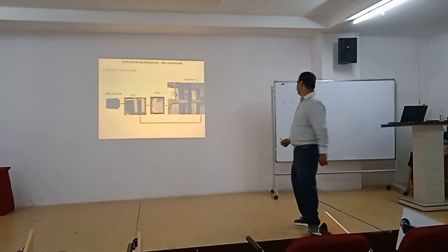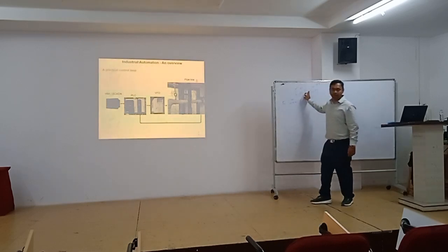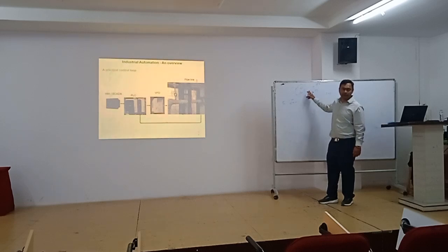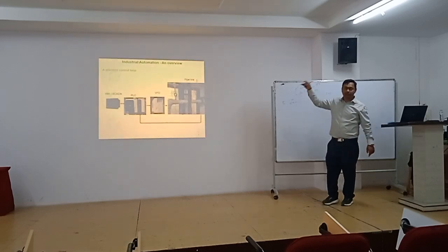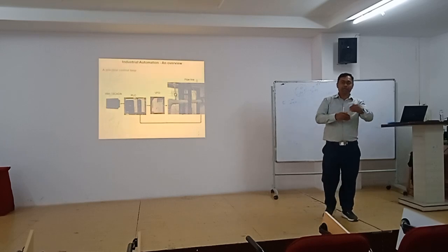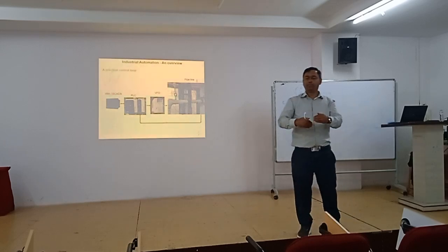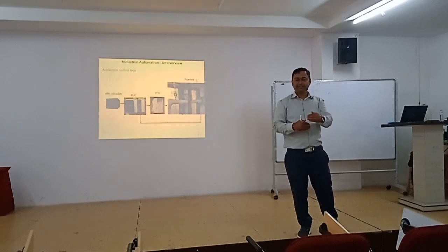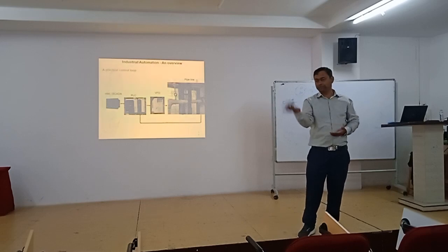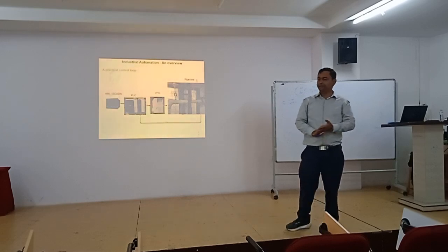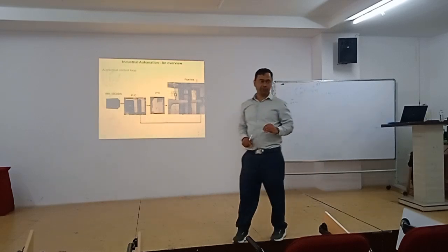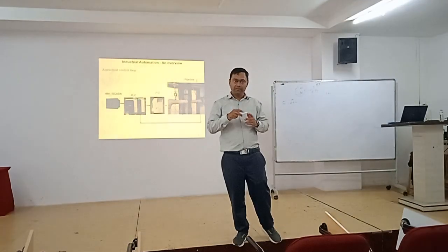The voltage, maybe sometimes 5.6 to 5.8, 8.7, whatever voltage is required, is decided by the PID. That's why you do the tuning. Ultimately, the final output is the voltage output from the PLC, and that will come out from the PLC analog output. Basically, the PLC has two types of input: one is digital input, the second is analog input, and two types of output.